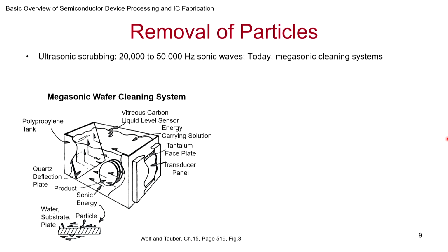Because of this vibration, bubbles are formed and they are again collapsed. As they collapse, they send out waves, and that ends up stirring all these particles and removes them from adhering to the surface and brings them to the solvent, and the solvent is replenished, so that way you get rid of them. Today you have even higher frequency, 850 kilohertz, in megasonic cleaning systems.